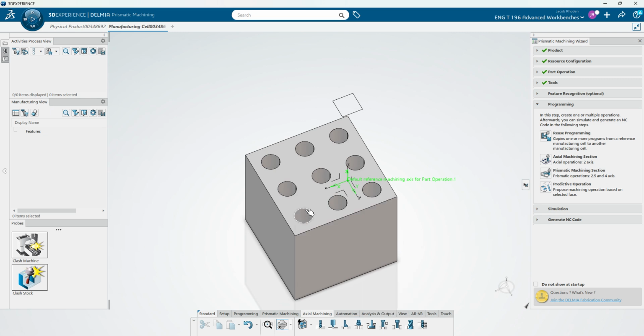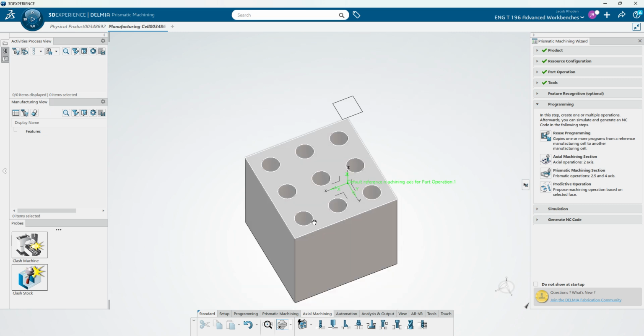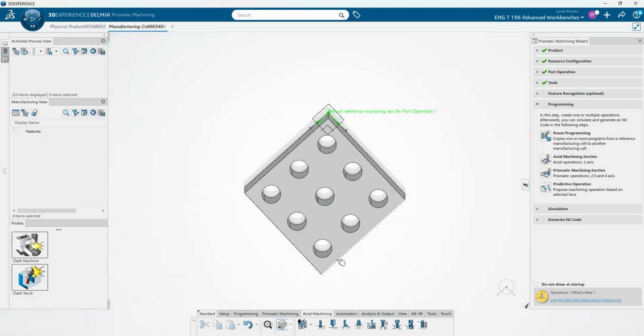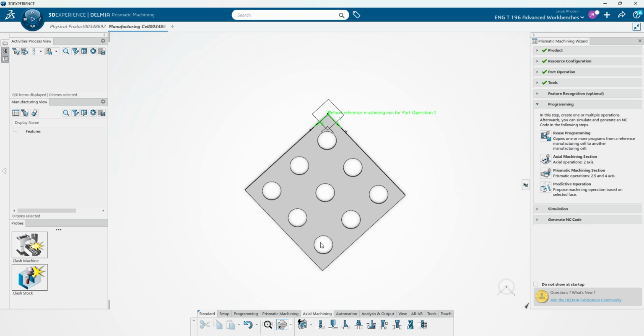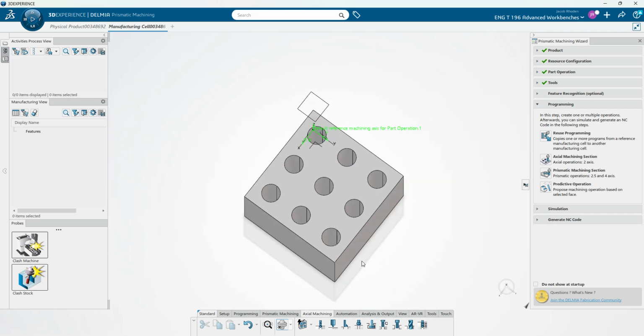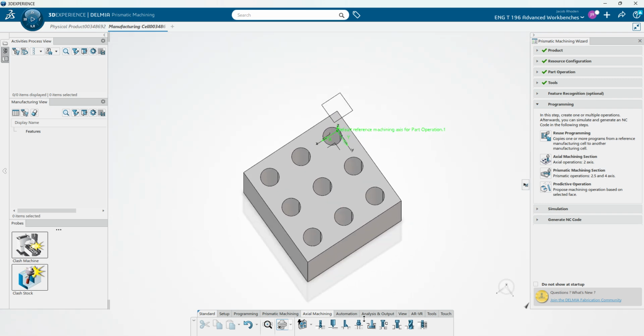So if you want to put a chamfer up here, or if you want to ream out a hole, so maybe you have another kind of tight tolerance, you could put a reamer through this and bring it a little bit closer without going through the kind of work and effort of boring, and get a little bit of a smoother finish than boring can give you.